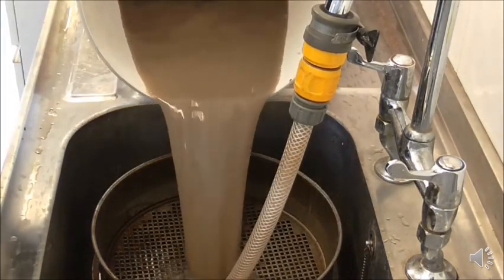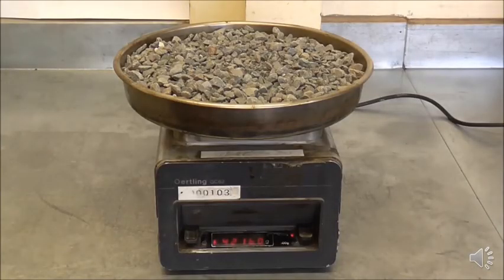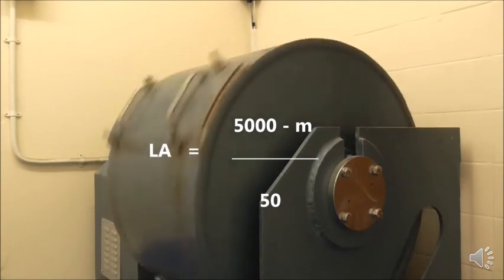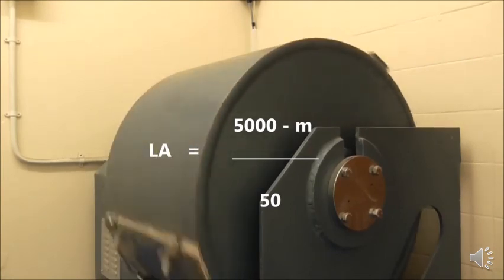That's because the balls have rubbed and caused friction, and a lot of the dust has washed away. So now we're going to just wash it, get all the dust out. We're going to place the aggregate back into the oven to dry it out. All the dust has been removed, and we're weighing it again, and look, suddenly it's only 4.2 kilograms. It's lost a lot of weight in dust.